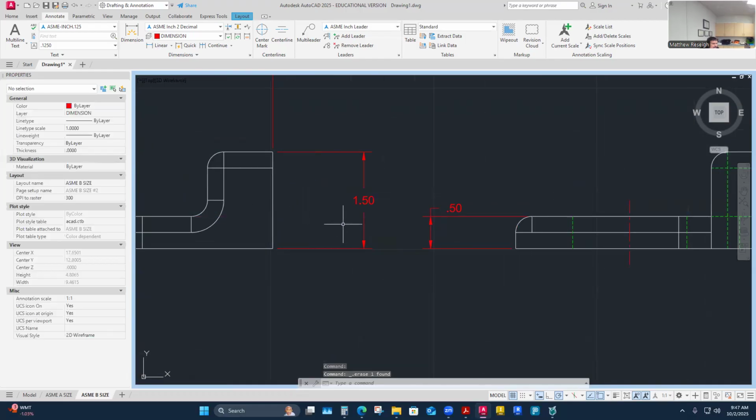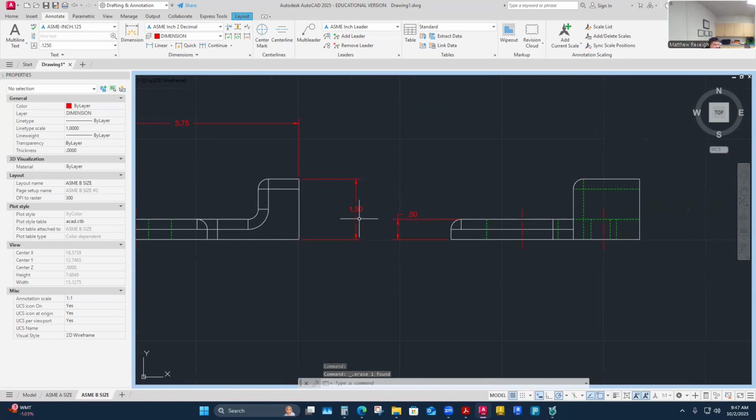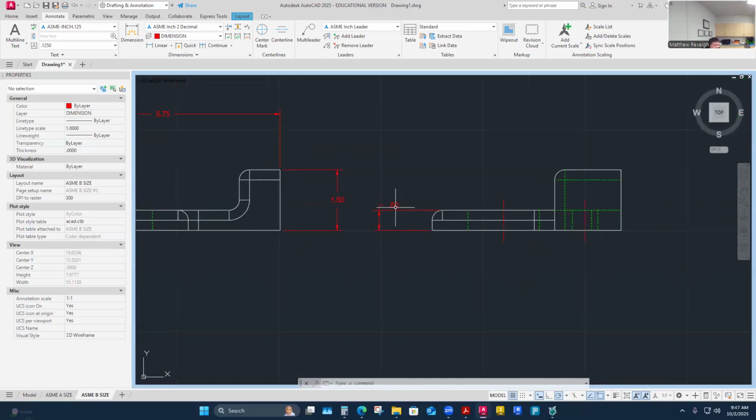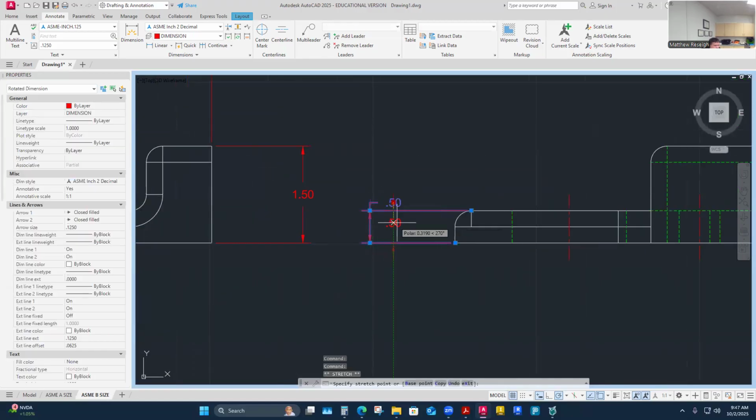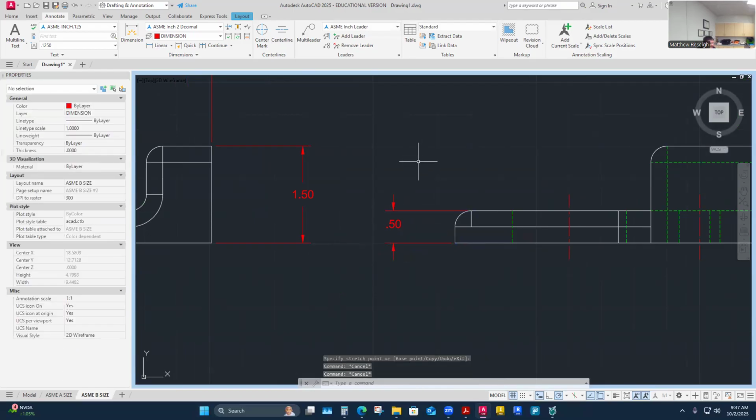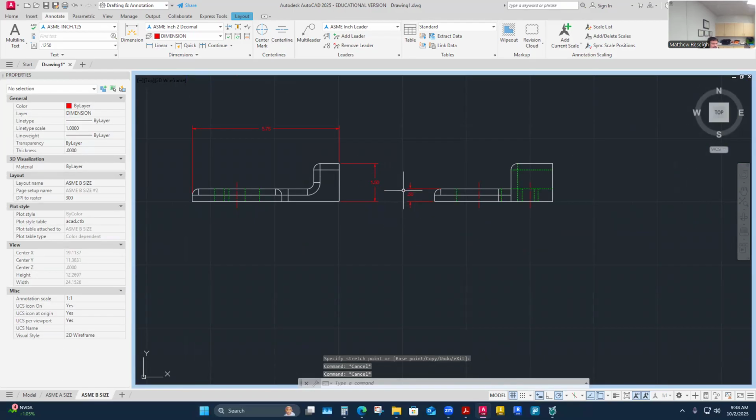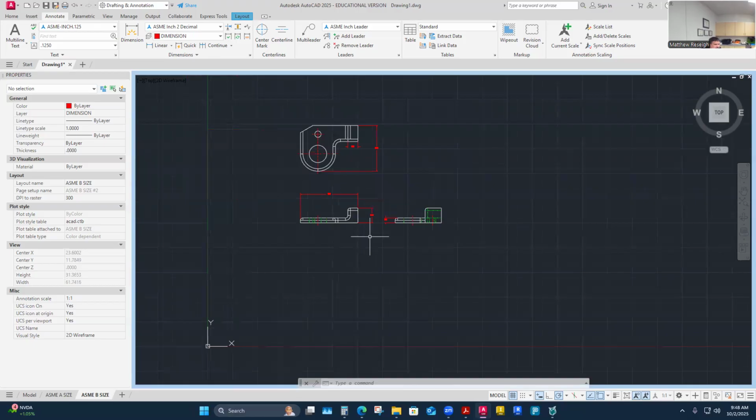And see what I've done is I've said, well, that is 1 inch now because from this datum it's 1.5 inches, and from this one it's 0.5. That means this is one, even without the dimension. I'm now pulling from the same point to get the same information, and I don't even have the extension lines going on. So to me, this might be a better dimension selection here. I know I've got to space them out and do everything, but I like these two pulling from the same base to define maybe that 1 inch that I was trying to worry about as part of the size of that feature.